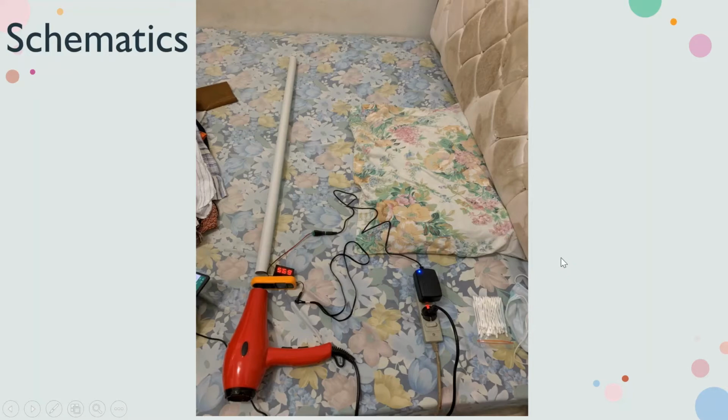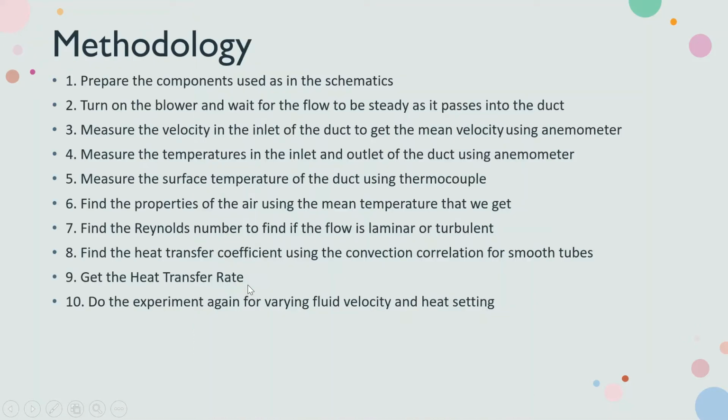Okay, so this is the schematic for the experiment, and as seen here, I placed the blower in front of the pipe inlet, and the thermocouple is placed inside the pipe, and the anemometer will be used to take the readings after the flow is steady.